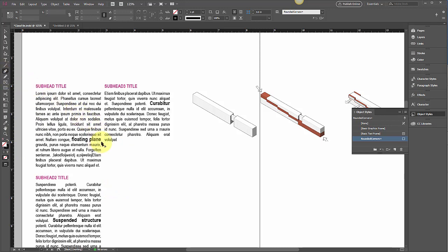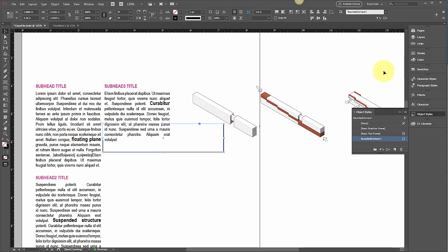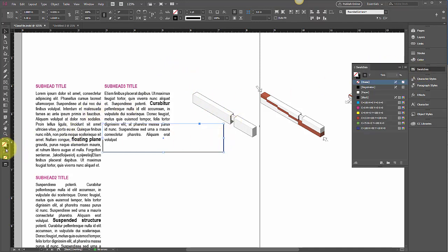Pen tool allows you to just select, up, over. I'm holding down the shift key. Holding down the shift key allows it to be orthogonal, so you go up and down and left and right. So I can do that. That's kind of cool. But let's amp it up a bit. Let's make sure that we're on the stroke.